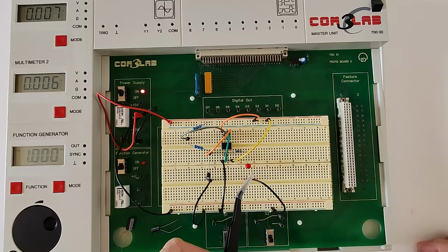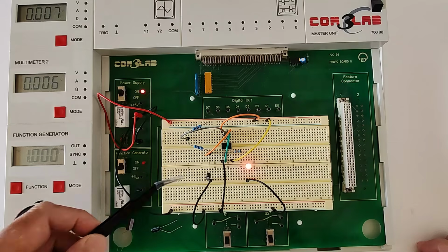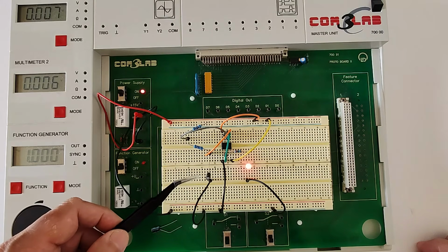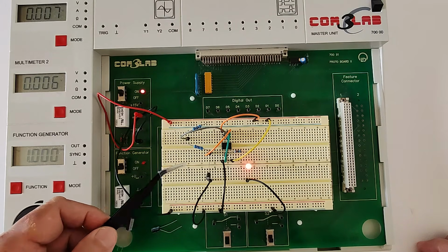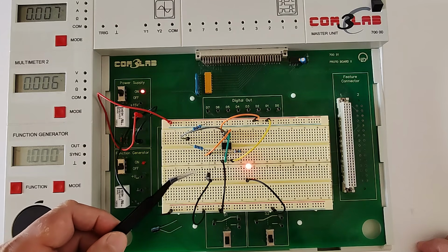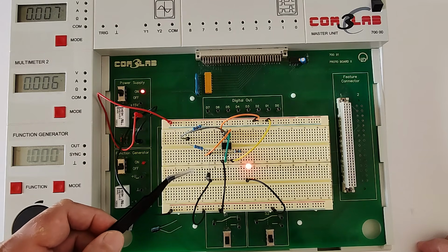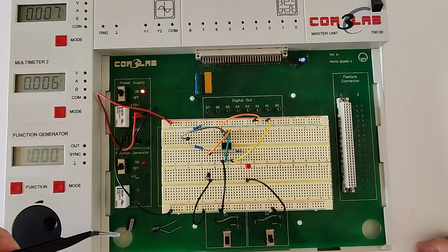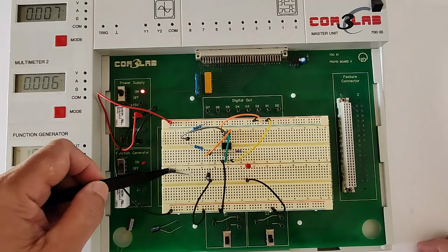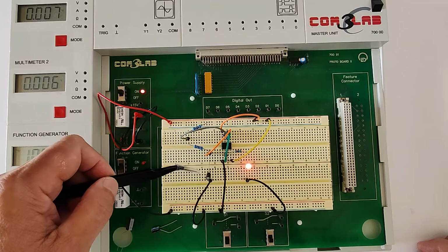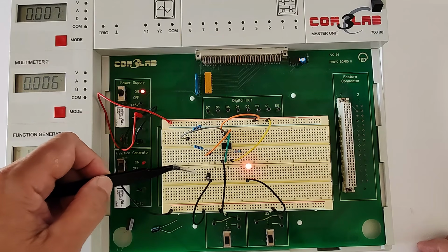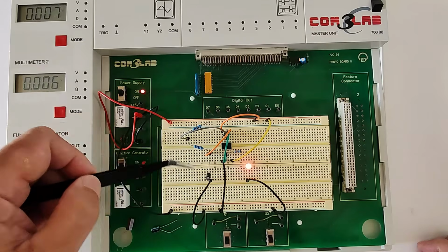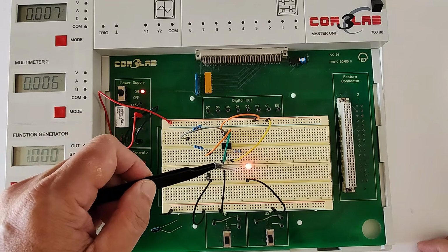As I've said, the time the LED spends in its on and off state is dependent on the charging and discharging rate of the capacitor. The higher valued capacitor will charge and discharge longer compared to a lower valued one. I'm referring to the capacitance value, the farad value of the capacitor. With the 100 microfarad capacitor, the original one, it's slower. And this one, a 10 microfarad capacitor, is 10 times lower than the original capacitor. See the blinking rate. It's a lot faster.